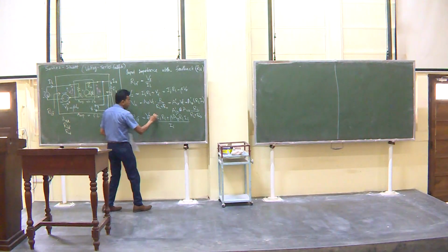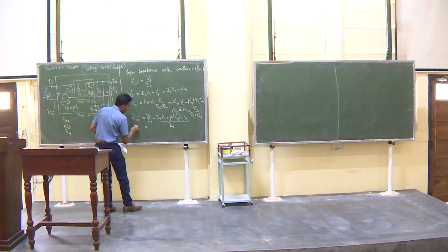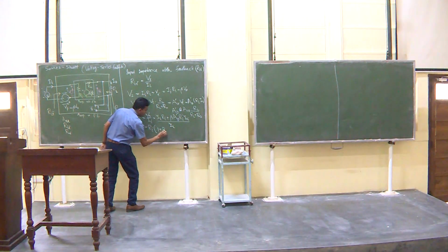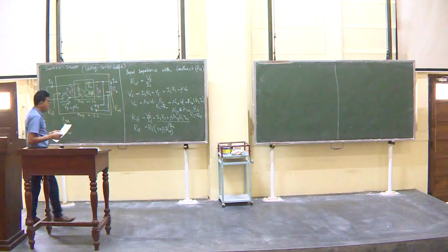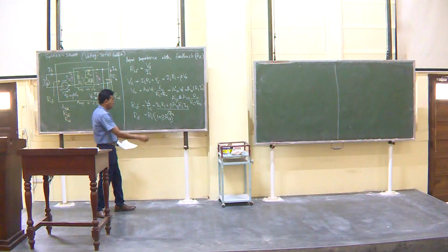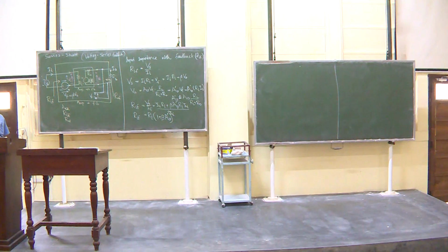So, you get rid of II and you end up with RIF equal to, I can take out Ri, 1 plus beta AV dash, 1 plus beta AV dash, right. Now, our expression was 1 plus beta AV, not AV dash, correct. The expression I gave you last time for the voltage amplifier was 1 plus beta AV.